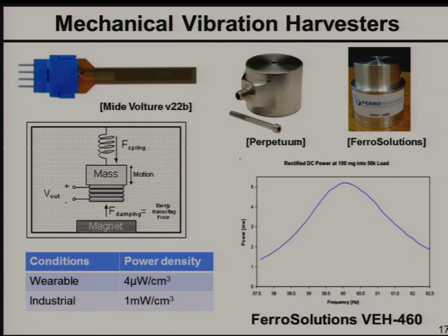One of the primary issues with mechanical vibration harvesters is that these need to be very high Q systems to extract proper energy out, to properly couple onto the mechanical side. And so when you look at it, the bandwidth is usually 1 to 2 hertz. So in an industrial setting where a machine has 60 hertz vibrations or so, it makes a lot more sense, where you tack on this harvester onto the machine and you're getting a few milliwatts of power. Now you can just monitor the machine, see whether it's operating correctly, do fault diagnostics, and radio the data out. So these are pretty useful in that kind of a system.